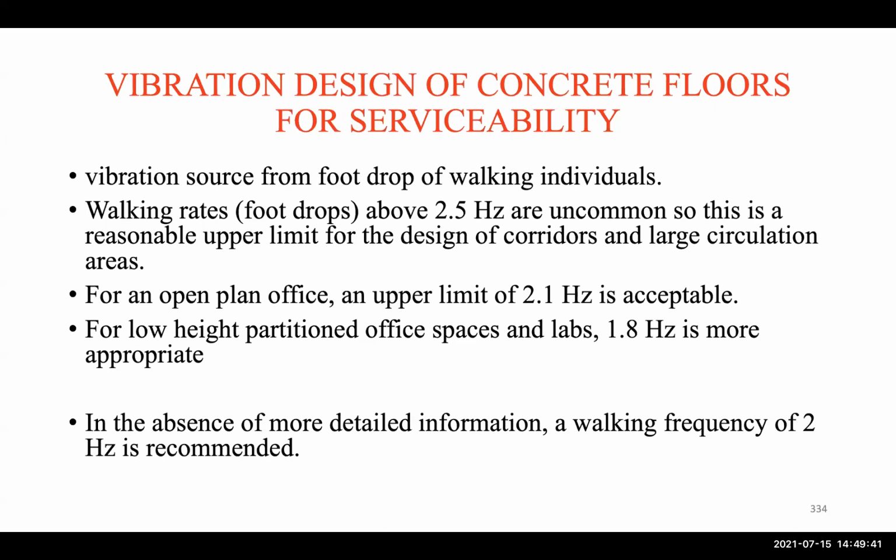Now, vibration source from foot drop of walking individuals. This is one of the things that we need to identify. That's the source, and walking rates that are above 2.5 hertz are uncommon. So typically we use that as an upper limit, and for an open floor office, we can use an upper limit of 2.1 hertz.